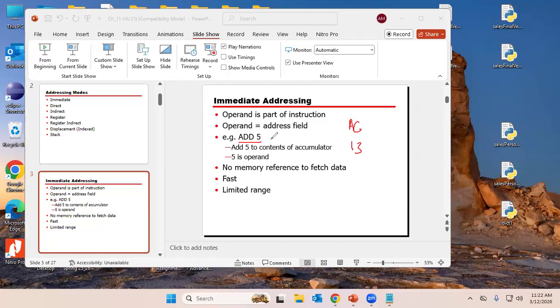There is no memory of 5 in front of it. So this is the constant that I was trying to introduce a minute ago. This is a constant, guys. So it will take the 5 and add it in AC, and this becomes an 18. So we have seen so far, for example, add indirect, where it goes to get the value, and we have add immediate, which will pick up the constant itself and do whatever you want to do with it with the AC. This is easy. And the characteristic of this is good. I call it a constant, guys. Meaning add memory of 5, comma, constant. We have something like this, guys. A minute ago, I drew it. So you can have add.